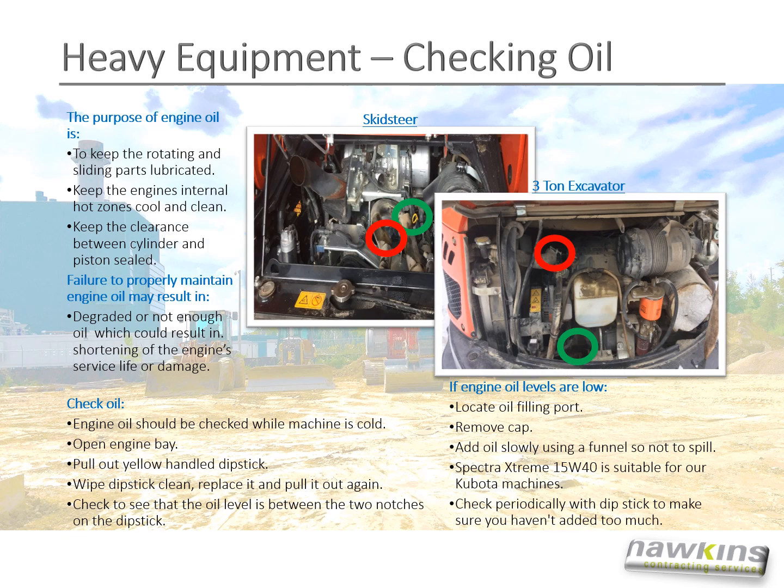If engine oil levels are low, locate the oil filling port, remove the cap, add oil slowly using a funnel so not to spill. Check periodically with the dipstick to make sure you haven't added too much.